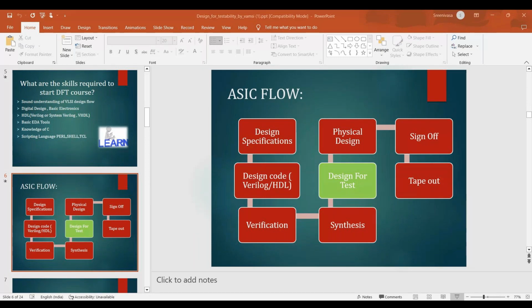So the testing engineer will not have the data for what to send into the chip to test it. We should only be responsible for generating the data and giving it to them. So it is not only that you are inserting the design, you're also activating the design, and you'll give the values of ones and zeros which need to be applied on the tester.